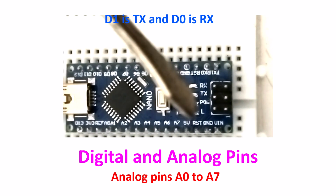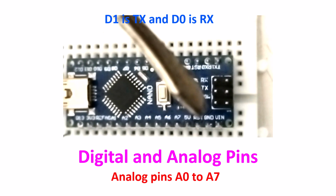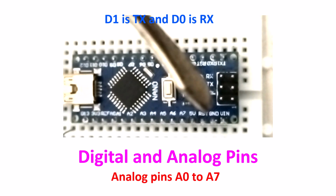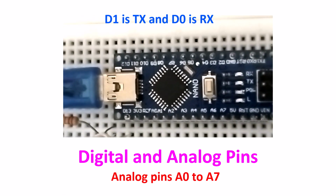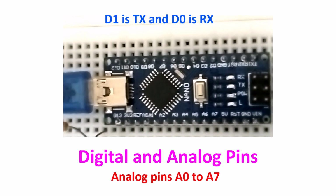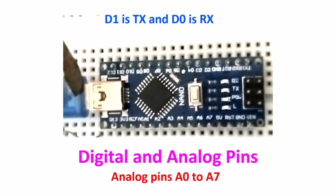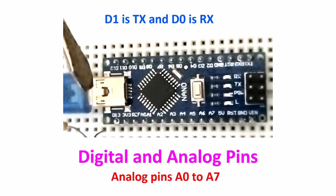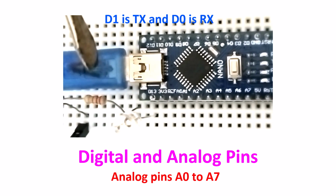Vin is the input voltage which can be given from an external power supply, other than what you can give through this USB port. I have been using mostly this USB mini B, or some call it micro B also, that I'll power usually from the power bank.